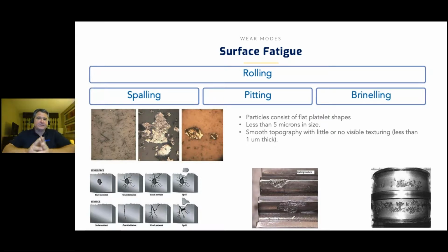Once there's a dent, once that roller ball bearing or spherical roller bearing rolls over that particle and that hard particle creates a dent in the raceway, as it continues, with that pothole effect, you're going to end up with subsurface cracking and ultimately spalling that shows up in your parts and shows up floating in your oil today.